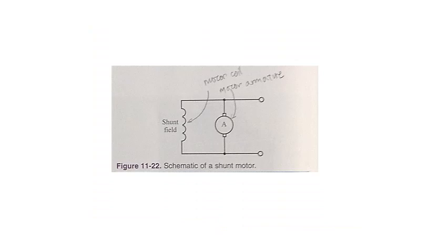(11.2) DC motors. The different types of DC motors share the common names of DC generators, such as shunt, series, and compound. The construction of the motors is similar to the generator counterparts. Shunt DC motor. In the shunt motor, the field windings shunt across, or in parallel to, the armature. See figure 11-22. The shunt motor is commonly called a constant speed motor. It is used in driving machine tools and other machines that require relatively constant speed during variable loads.